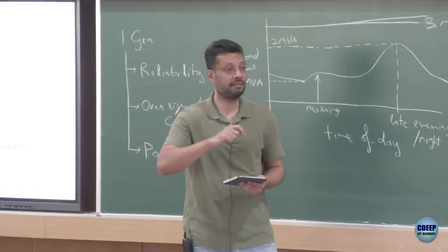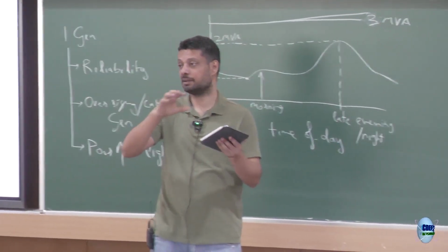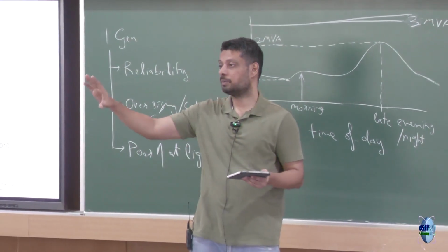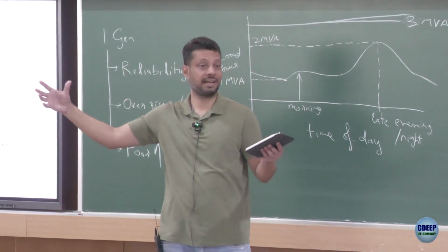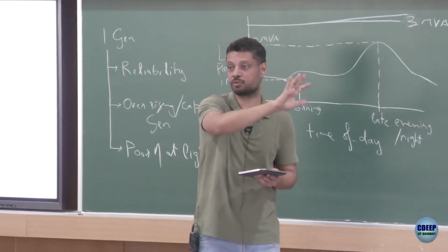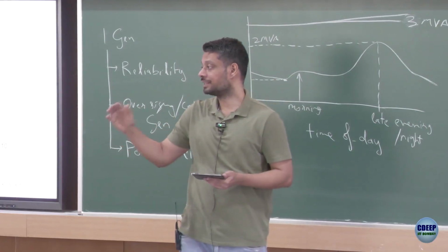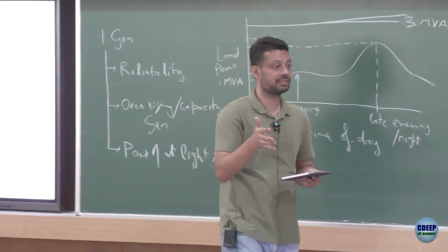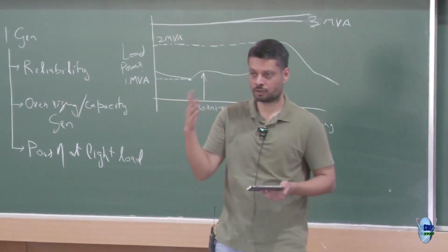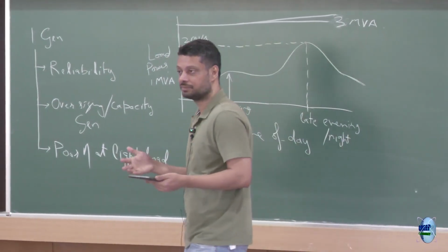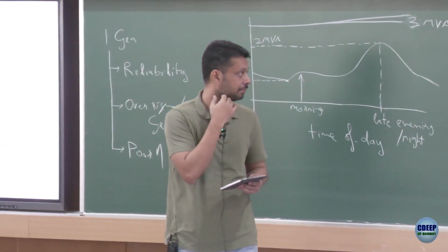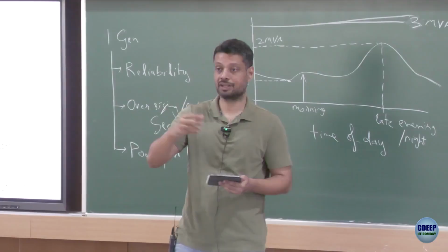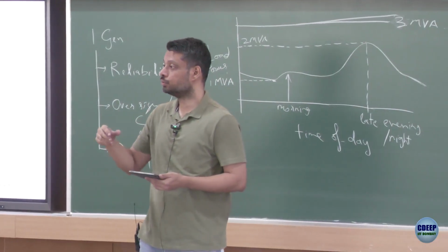You can have 2 grids, connect them, have a rectifier, pass on the power as HVDC, and then have an inverter. There still you can make sure the power flows from one grid to another grid. But that is asynchronous. We call it asynchronous. Why? Because the frequencies on both sides need not be synchronized. But what I am saying is that in December 2013 the whole country got connected through a synchronous link.